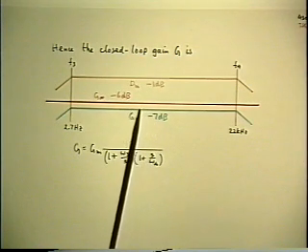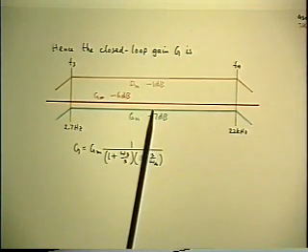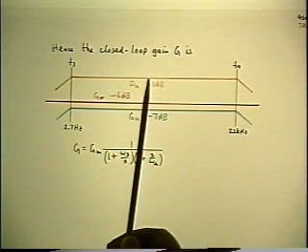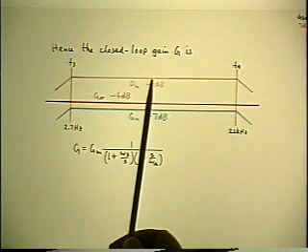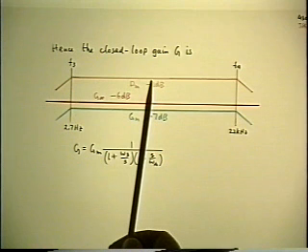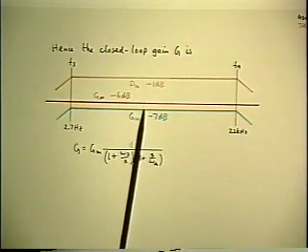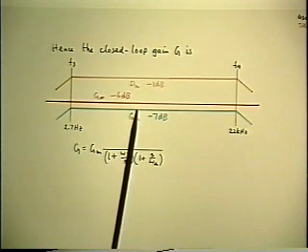And the deviation, even at best, is 1 dB away from the ideal value or the specification, because the mid-band loop gain wasn't that high anyway. It was only 20 dB. So Tm over 1 plus Tm is 10 over 11. So that's 10% less than 1, which is why you get a 1 dB discrepancy.